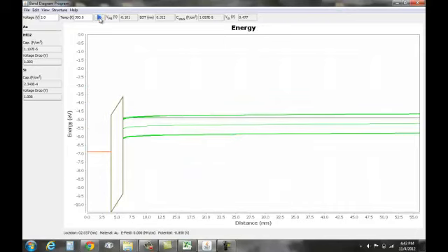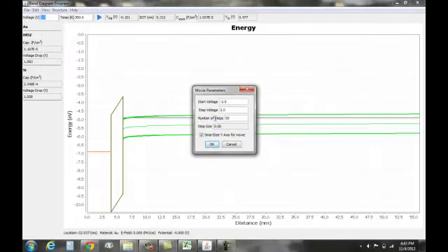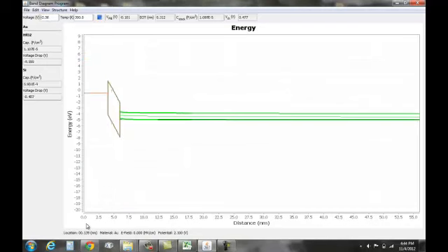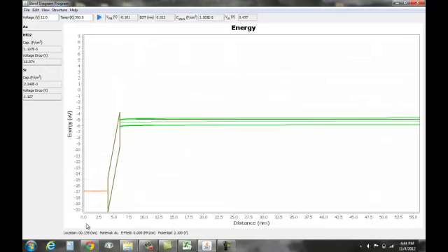And you might ask, well, I'm doing a voltage sweep from what voltage to what voltage? In order to determine that, I'd have to go under View, Parameters, and see that I'm going from -2 to 2 volts. If I wanted to go from -12 to 12, I can certainly do that. It provides the opportunity to change the number of steps if I wanted to. That's fine. I can select it, and the y-axis changes to allow one to see the full voltage sweep, the entire band gap.